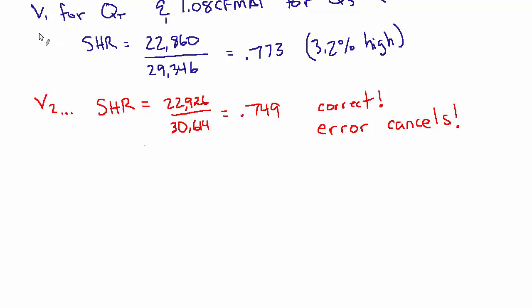And then the other part is regarding the rule of thumb and what it actually means to use 1.08 CFM delta T. So as a reminder, I've talked about this in other videos, but since it comes up so often, what's baked into this 1.08 is the 60 minutes per hour and the density of air at a particular temperature, which is arbitrary, of 0.075 pounds per cubic foot, and the specific heat capacity of air, 0.24, which is relatively unchanging with temperature.